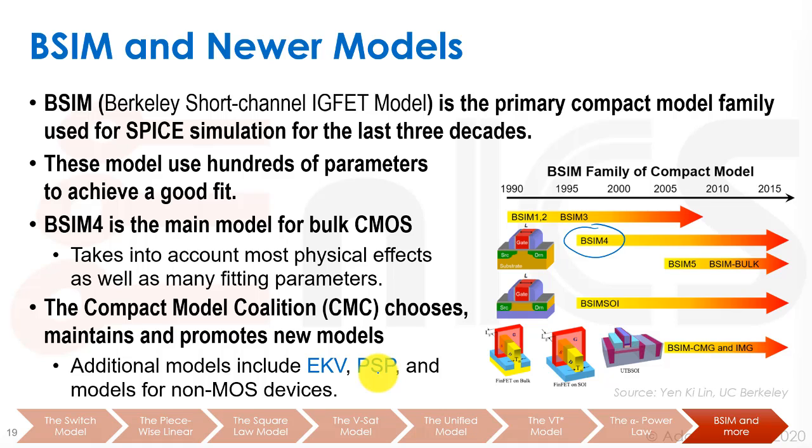Nowadays, we can't use the standard BSIM anymore because we've gone over to non-planar transistors such as FinFET transistors, tri-gates, gate-all-arounds, and FDSOI. So BSIM has put out BSIM SOI, and we also have BSIM CMG for multi-gate or tri-gate transistors, or FinFETs, whatever you want to call them. In addition, other models will try to take that into account. Plus, we have models for BJTs, for STT-MRAM, and other types of devices.